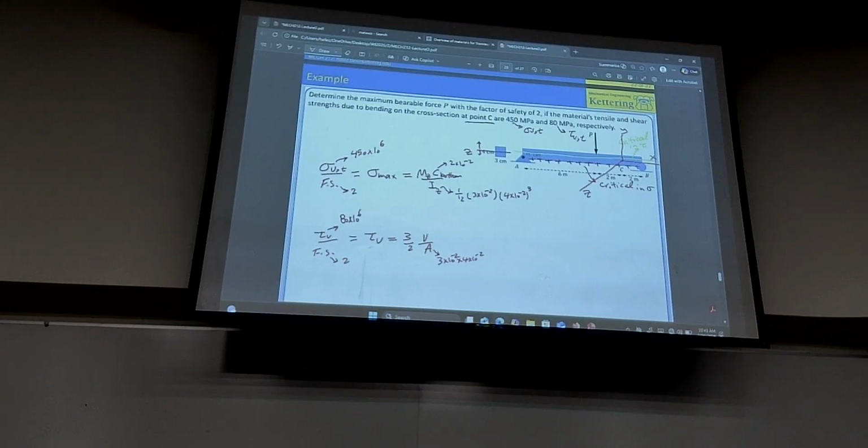All right, so the thing is this. M and B should be related to the force, which is P. M and B are applied at C, but P is applied at another point. So this means we really need to do static analysis. So I'll let you finish this, but then you want to go to the next slide, do static analysis, figure out that dependence between P, M, and B, and then it all goes back into these two equations and then solve for these. But before that, write this down.